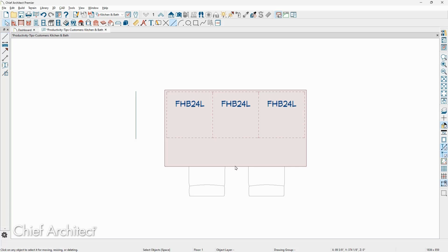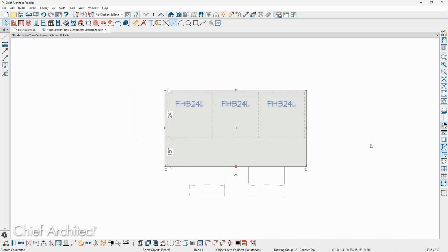Let's look at the temporary dimensions, controlling the location and the style. I began the seminar talking about hotkeys. If I press the letter T on the keyboard, you see them go on and off. That tool is also off to the right hand side of my menu. You see the temporary dimension. It does the same thing. The hotkey saves me a step in going over there.